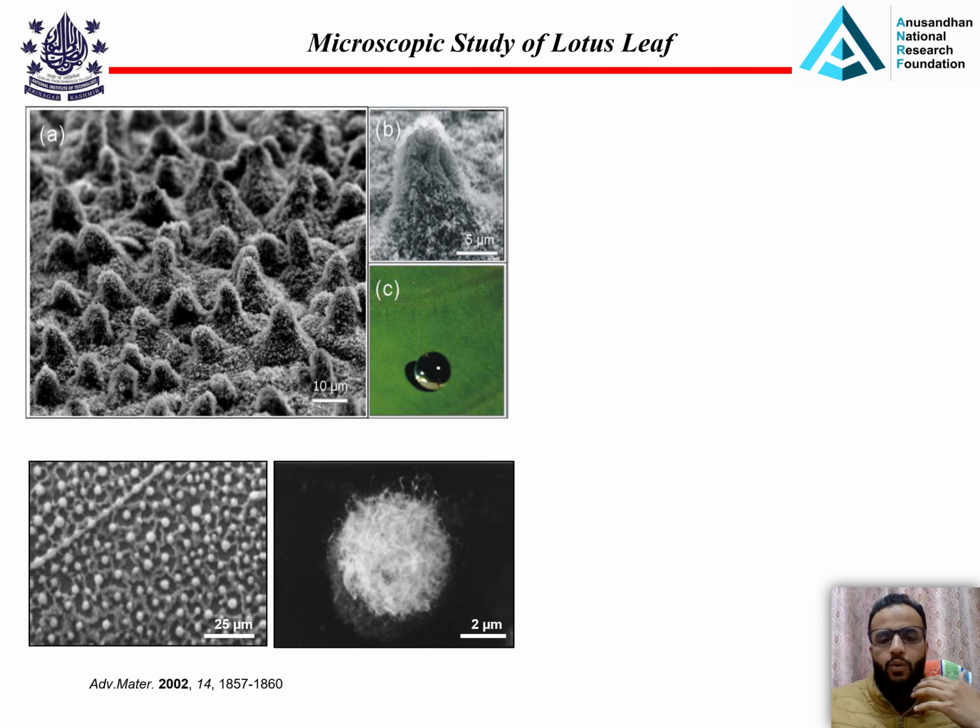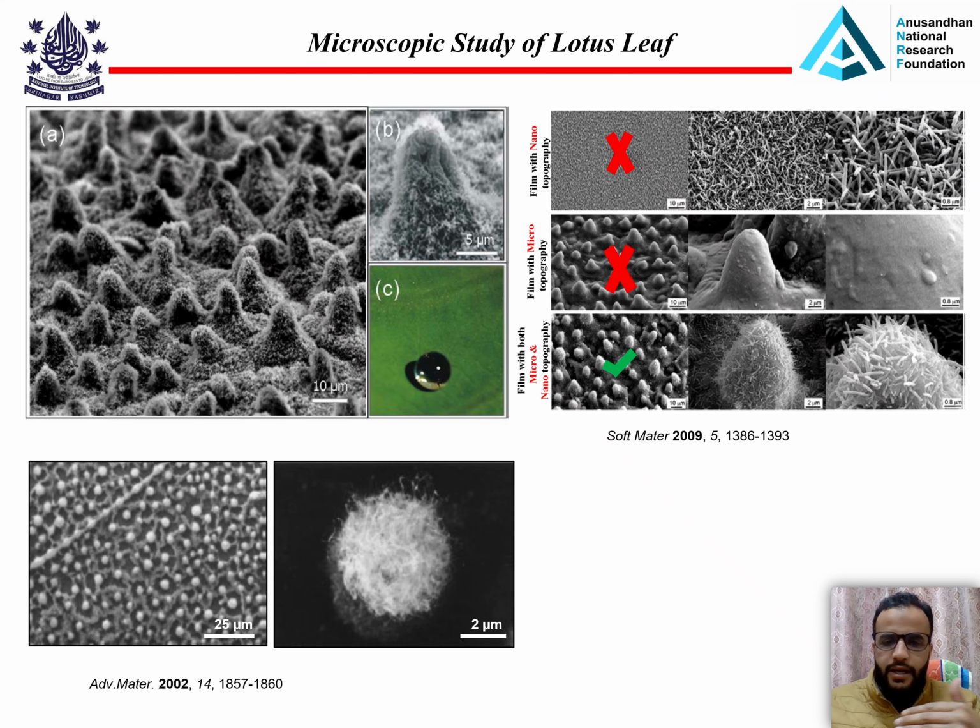Eventually, this was replicated by artificial means, and researchers designed different micro nano textures to replicate the lotus leaf structure. It was found that an appropriate combination of micro and nano texture with an essential low surface energy coating provides super hydrophobic materials.